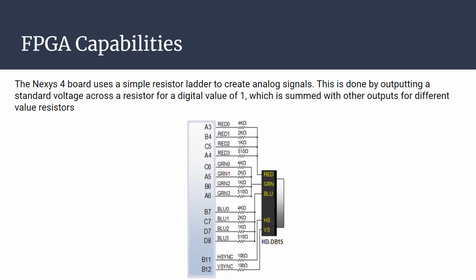So we do have a lookup table to actually map those 3 bits and 2 bits, based on which color it is, to the 4 bits that you see here, so that we can get the full intensity of red, full intensity of blue, and everything in between as much as possible within that resolution.